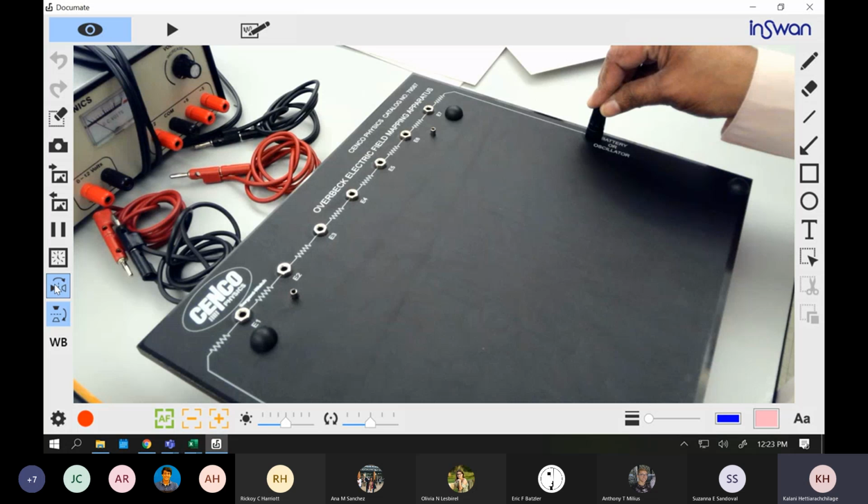And now again, the voltmeter we're going to use is the voltage, right? So I'm going to keep it in here, but you can keep it by the side. I need to show them how to connect this one. Take the other red wire and you're going to connect that red into the volt knob, that is the last one on your voltmeter. And then the other side of this wire we're going to connect into E1 on your field.